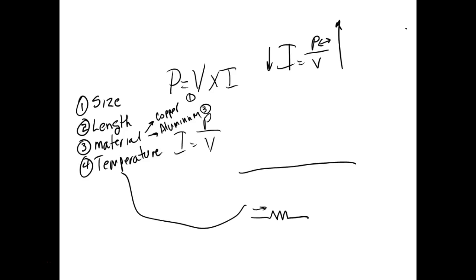So this is the advantage of DC right here. I can electronically control it. AC is real hard to electronically control. We can step it up with transformers, but that's not electronics, and we can step it down. But electronic control means I can take DC and I can generate AC if I want to. So you can buy a thing for your car called an inverter that you hook up to your battery, and you get 120 volts AC out of that because it's done electronically, right? You understand that?